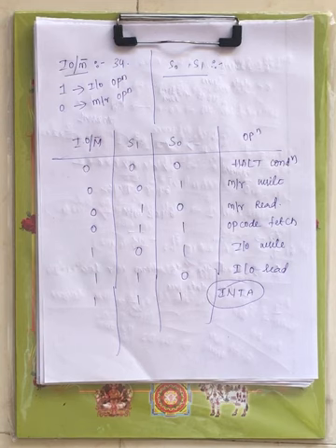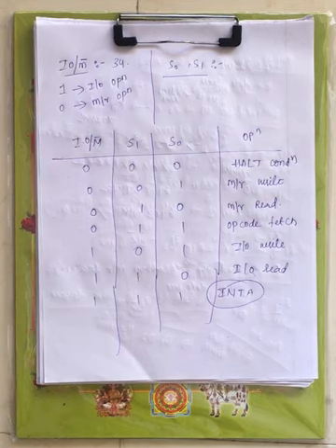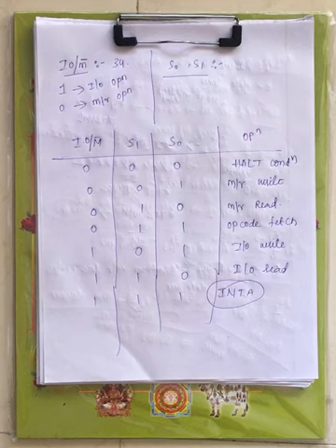Now meanwhile you remember, IO slash memory bar is coming to the 34th pin. When it is 1, it indicates IO operation. When it is 0, it indicates memory operation. And next we have status signals S0 and S1. Based on this you have a table. Now S0 and S1 will give the status of a microprocessor. That means whether it is writing the operation or reading the operation, that particular status is given by the status signals S0 and S1.